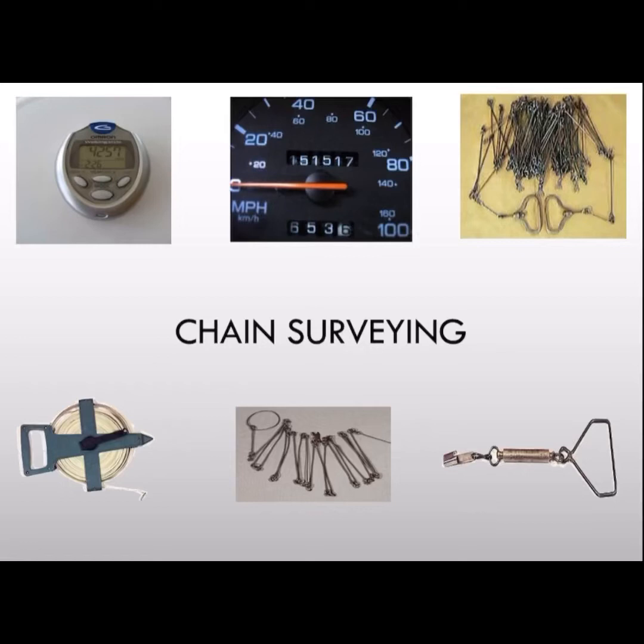Our topic today is chain surveying, and the chain survey is the simplest method of surveying. In the chain survey, only measurements are taken in the field, and the rest of the work, such as plotting, calculation, etc., are done in the office. And here only the linear measurements are done. And I will show you.